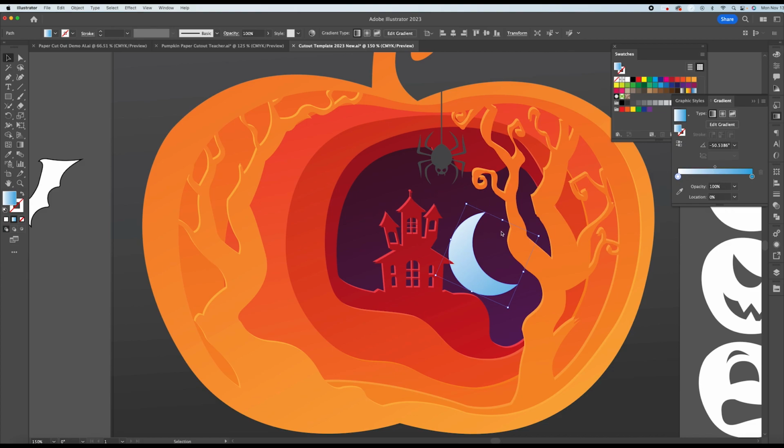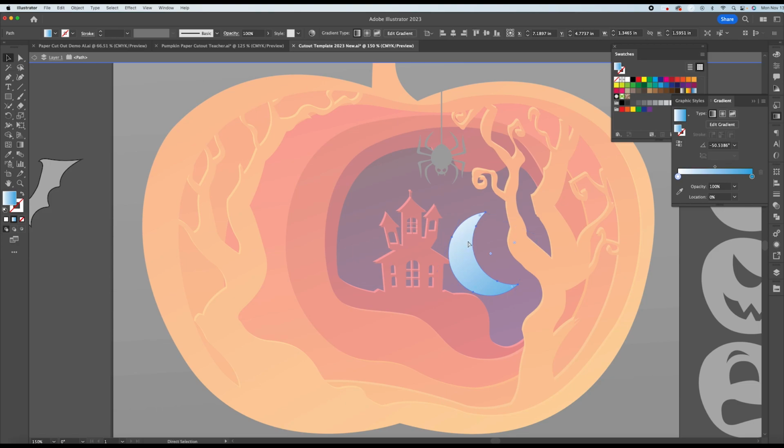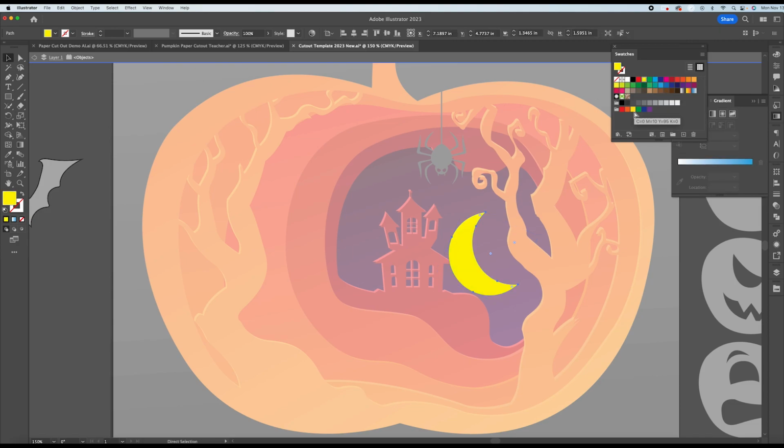But now that I have this, if I wanted to create a highlight, double click on the piece, Command Control C, Command F, make it yellow, Command F again, make it white. Up to the left, select on the yellow, select on the white, then use the shape builder to cut out the areas of yellow and the overlapping sections.